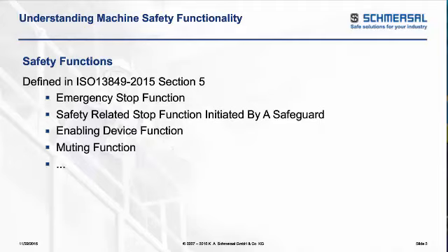You have guard doors, light curtains, things of that nature that you're trying to use to put the machine into a safe state for operators to safely open up the door, do what they need to do for their production, their process, and come back out, close the door, and restart the machine again, but under a safe condition.